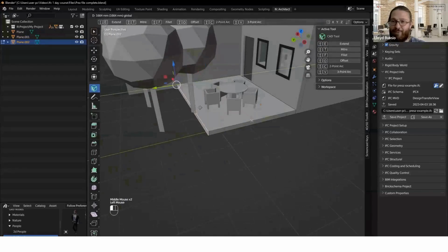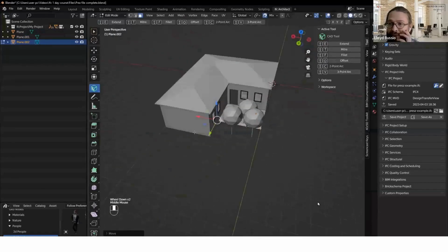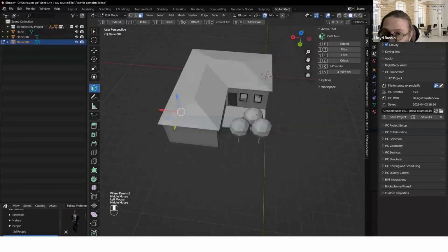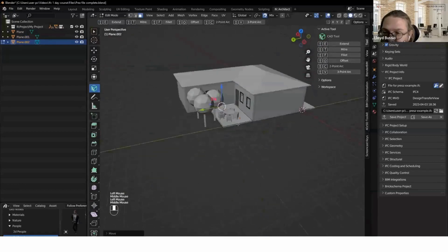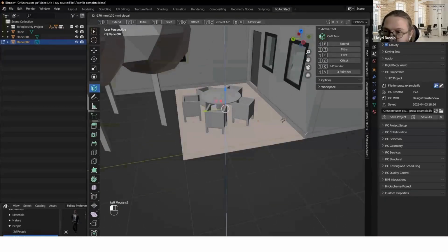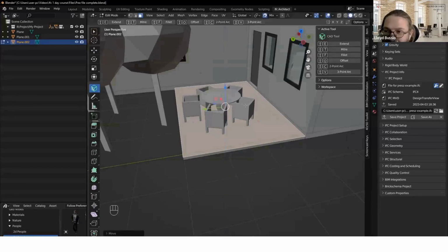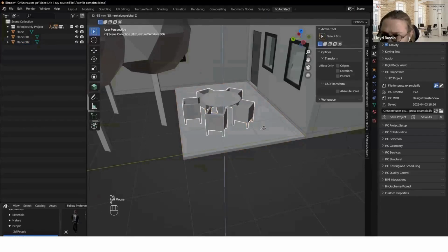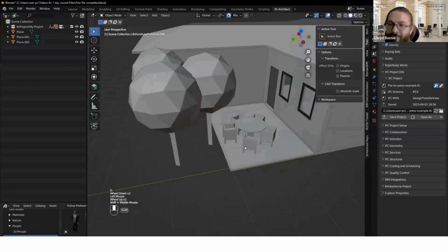Here you can see I'm just adjusting this porch portion here, just making it a certain size and then adjusting. So I'm just pulling and pushing edges here and making a porch that is higher. I think I bring it down by a step. So I just say -85, which is like half a step. And then I snap the 3D geometry.